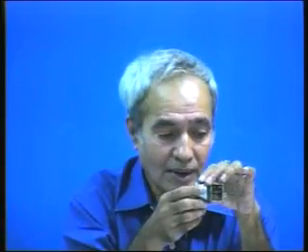So let us look at it again. The servo motor essentially consists of a motor, a gearbox, and the electronics mounted on the back of the motor in order to accept computer commands. Then there is a feedback element. We will see what that feedback element is, which feeds back the position of the output or the position of the input, whichever it is, depending on how you have configured your motor, to the controller. Okay? And then the voltage or the current through the motor are adjusted by the controller in order to get the requisite motion.